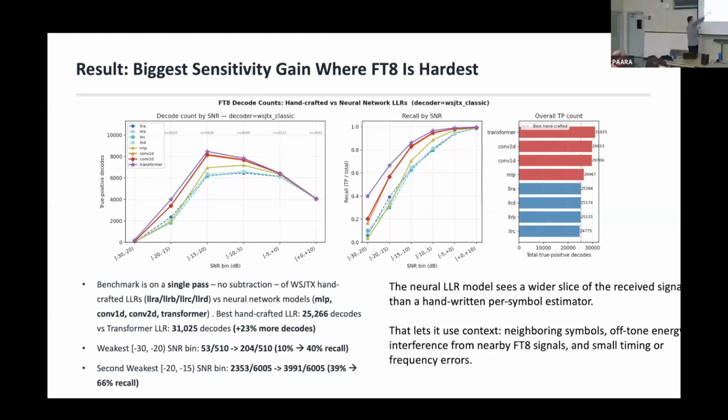The reason you see this shape is because in the real WAV data, the actual band conditions, like all these WAV files that I'm talking about, this is where most of the signal to noise ratios are that are reported on my machine when I'm recording. So between around -20 and maybe up to 10. And then it's only somebody who's got a really big antenna and they're in, like, I don't know, Los Gatos or Mountain View or something, and you get a plus 38 on there, and I still call them on WSJT-X if I want to make that contact.